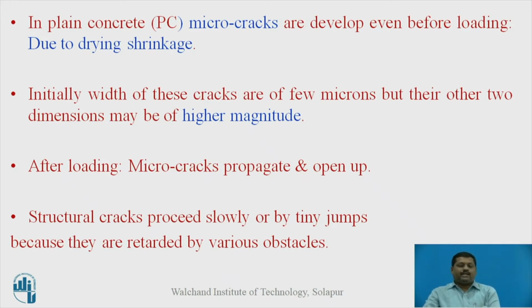One more important thing is that initially the width of these micro cracks will be very small, a few microns. But the other two dimensions, depth and length, of these cracks will be of higher magnitude. In case of structural cracks, these proceed slowly. So the crack is a major problem in our regular concrete.